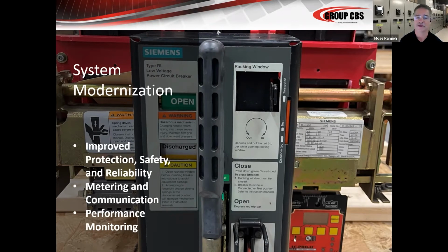What's special about taking advantage of some of these modern trip units is, one, from an arc flash standpoint, they're more selectable, right? I can have down to a few amps. We can adjust that current and make both better coordination and lower arc flash let through because of the settings that we can put into these trip units. The other nice feature about the AC Pro 2 over the AC Pro 1 over any other retrofit trip unit that I'm aware of is they have what's called the sluggish breaker feature.